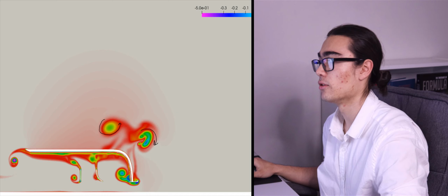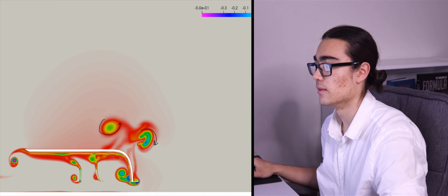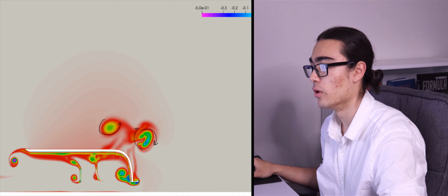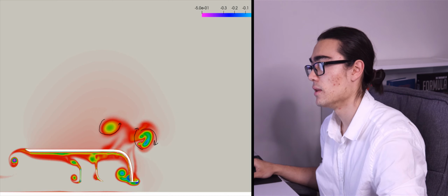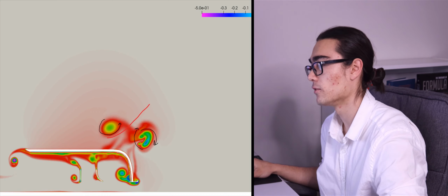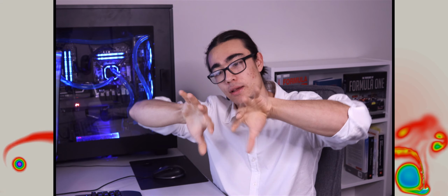Now these are counter-rotating, so there's a central part in the middle where they're both working together, and what this can do is take a lot of the flow from here and pull it straight through that gap like that. So with this system, if we work the canard vortices together, or in this case our canard vortex and our turning vane vortex together, we can effectively squeeze some air in between and shove it up and out of the way of the front tire, and this could be an effective means of generating outwash. And this is what's happening in this example.